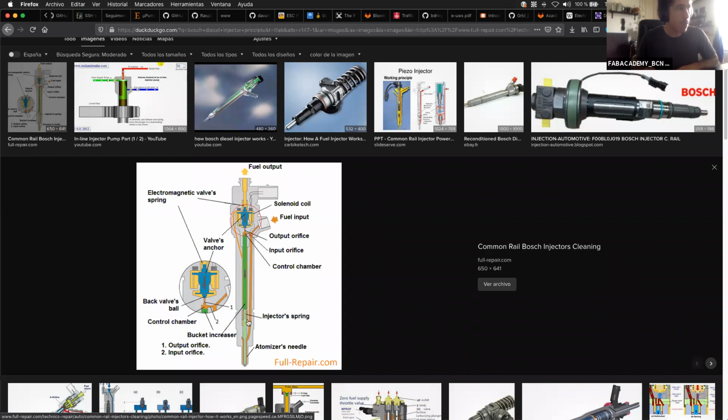Here you have high pressure fuel, and up here you see again the solenoid coil. Basically you have a coil that is activated with two wires, not very much energy to activate this thing. The coil, when activated, moves this plunger, and that creates a little bit of hydraulic balance inside the injector that opens the needle, and then it allows you to inject.